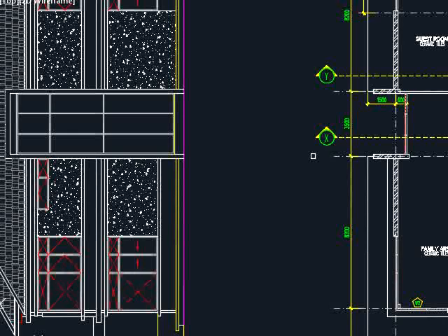There is no right or wrong in terms of whether you want to make it reinforced or you just use brick walls. However, the important part is you will need to make sure this entire thing is stable. If you have no confidence in the stability of the brick wall, probably you just provide reinforcement bar as reinforced members to ensure this is in one piece.